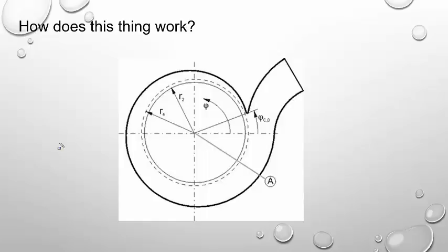So if I go back to my Q equals V times A, I'm going to have to write this up here again. Pardon me for just a second. Okay, so Q equals V times A. I know it's painful watching me do this, but it's the best I got, people. I don't want velocity. I want velocity to be down. What do I need to do with A? Inverse relationship. I need to increase it.